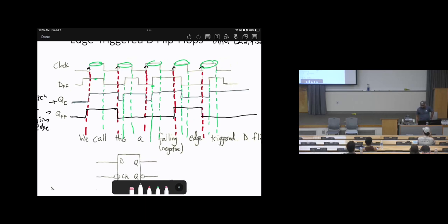Can you explain why on the flip-flop, on the middle rising edge, it doesn't flip? Which one here? So on QFF. Yes, the middle red. Do you mean this one? Yeah. Okay, let's see. The first rising edge, D is 1, therefore it is 1. You agree with the first one, right? Let's go to the next one. It will hold until the next one.